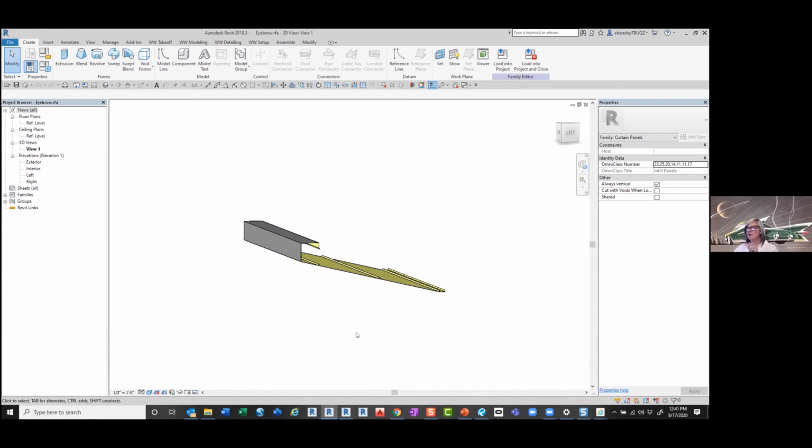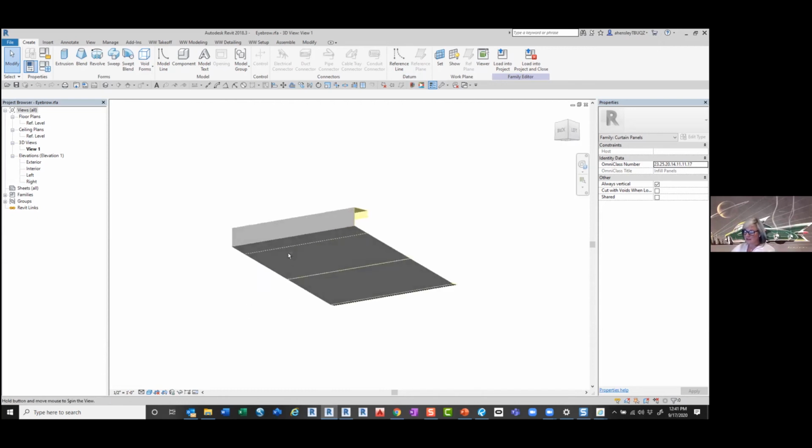The problem with that, the issue, the downside, I guess, to be diplomatic, is if that profile changes, because now it's gone to drafting, they have to update the mass and change these different panels to what it's really supposed to be. That can be a much longer process for drafting, especially with these eyebrows that wrap all the way around the building. So if we're saying this is not a great way to go, even though it's faster for drafting, the option is they have to build masses and apply stuff to faces most likely to get these sloping surfaces.